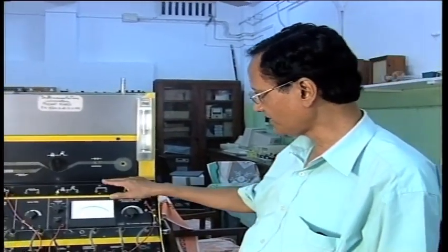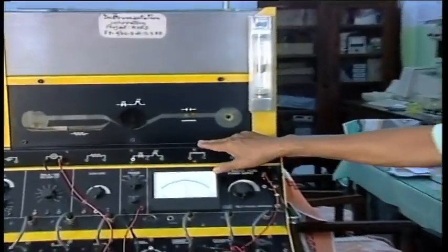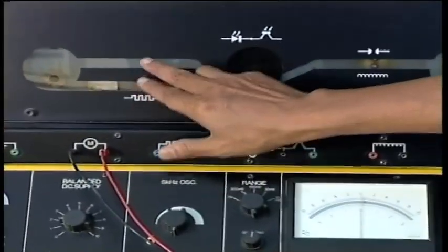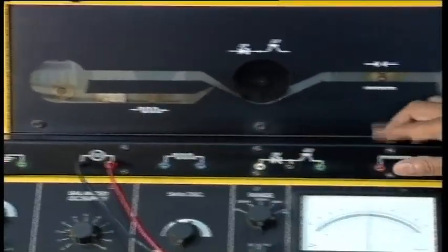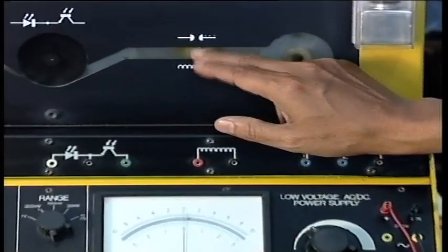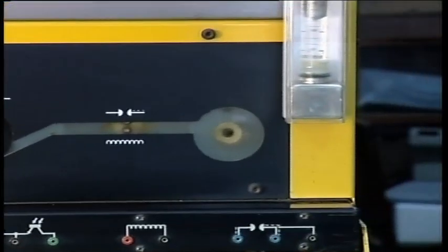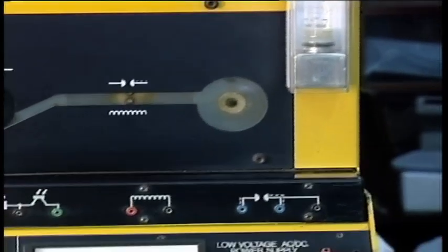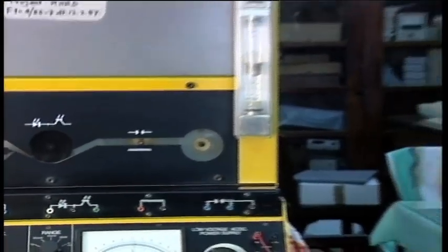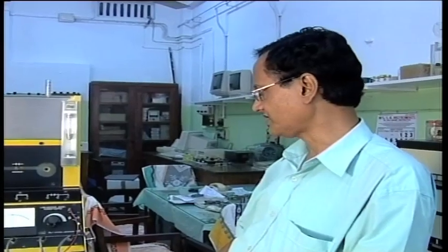Similarly, the hot wire anemometer also has electrical output, and this is the hot wire anemometer. We cannot see it from here because it is inside. And the magnetic flow meter also has electrical output. So all these flow meters except this rotameter have electrical output. Now, electrical output has advantages. If you have an instrumentation system, with electrical output you can directly convert that signal to the current domain, 4 to 20 milliampere. Then you can digitize this if it is necessary.